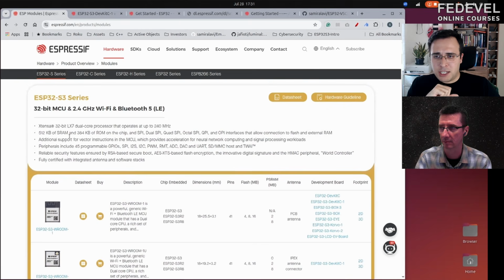They have a large SRAM and a large ROM, but usually the ROM is not used, and we usually program the flash that is externally extended, though it is inside the SoC package, and there are different variations we will cover. This flash is connected through SPI lines. Sometimes it is dual SPI, quad SPI, or octal SPI.